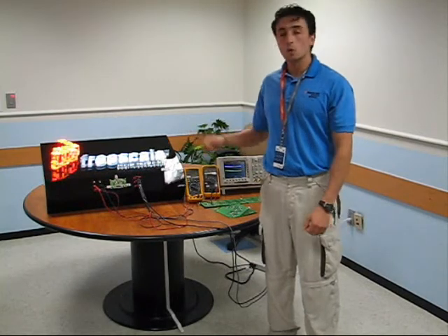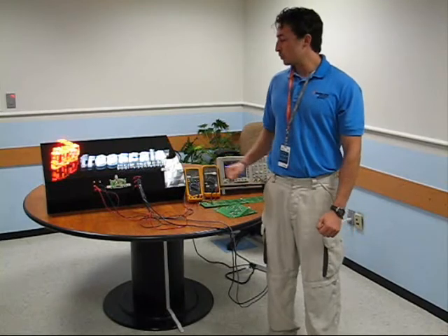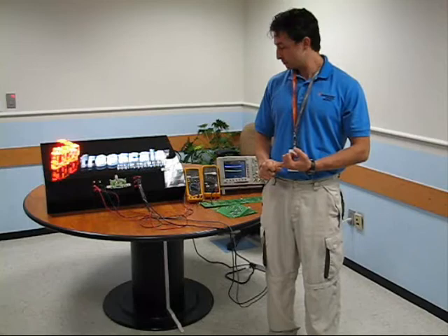Now to obtain the efficiency of our power supply, we divide the output power by the input power. This way we have 27 divided by 32, which comes out to be 85%. This means we have an 85% efficiency. With this we reduce heating and have better power consumption.